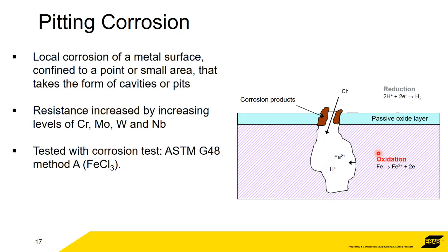And then what happens is that the pit turns into the cathode, the metal turns into an anode, and you get an electrolytic reaction that starts to eat away and create a pit. So on the surface, the damage doesn't look too bad, but underneath, a bit like an iceberg, it's much bigger damage.